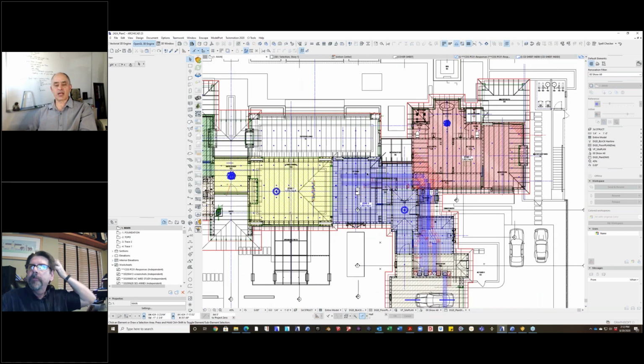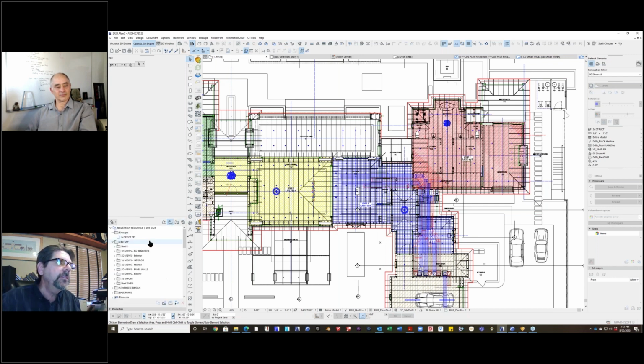So in your template, about how many of those do you have? Well, these are not templatized. They wouldn't make any sense. So how do I come about those? I'll jump into a section and see what my void is. I can draw right there in the section the fill pattern that is what I want, bring it into the profile manager, and make it a truss. So it's a custom part for each project.